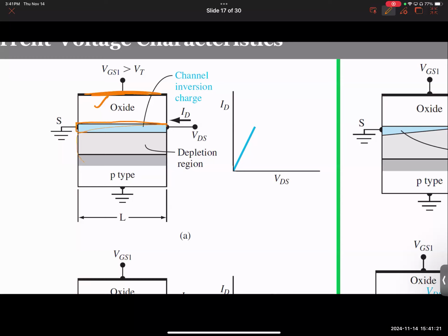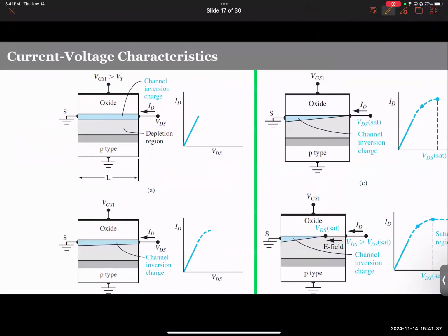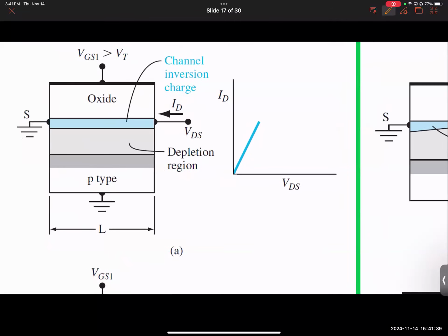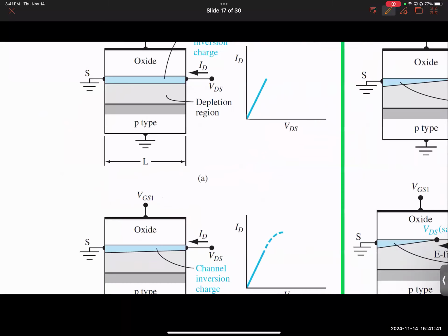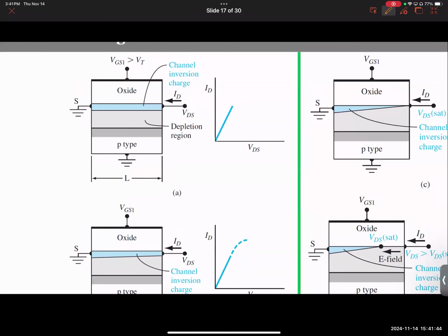This is, again, like a cartoon. We have basically ignored the source and drain here, but imagine they're here. S represents source, D represents drain. It's not me, it's a textbook, by the way. I'm just explaining what the textbook shows. Notice this. You have applied a gate voltage which is greater than the threshold voltage. You create an inversion layer.